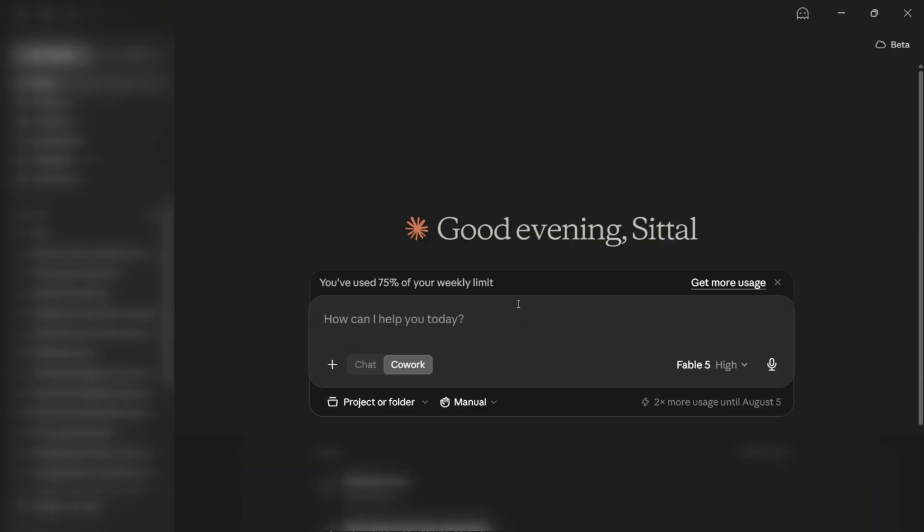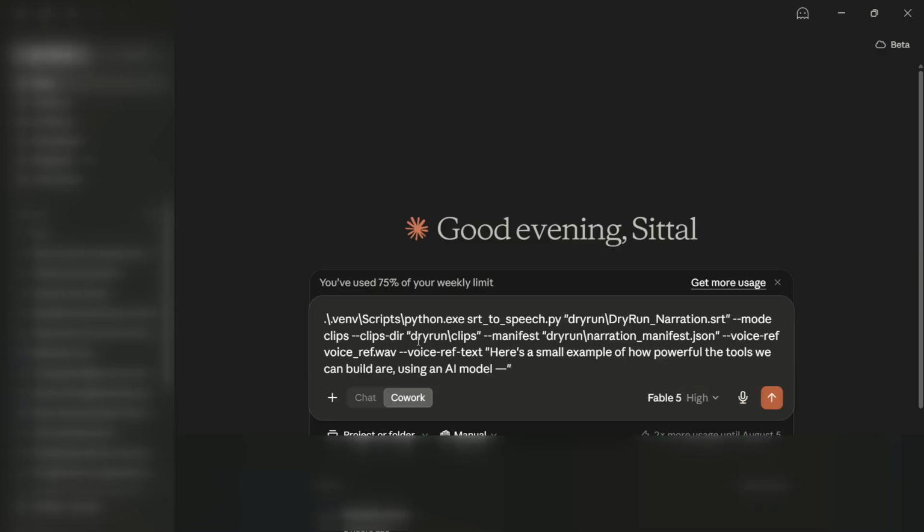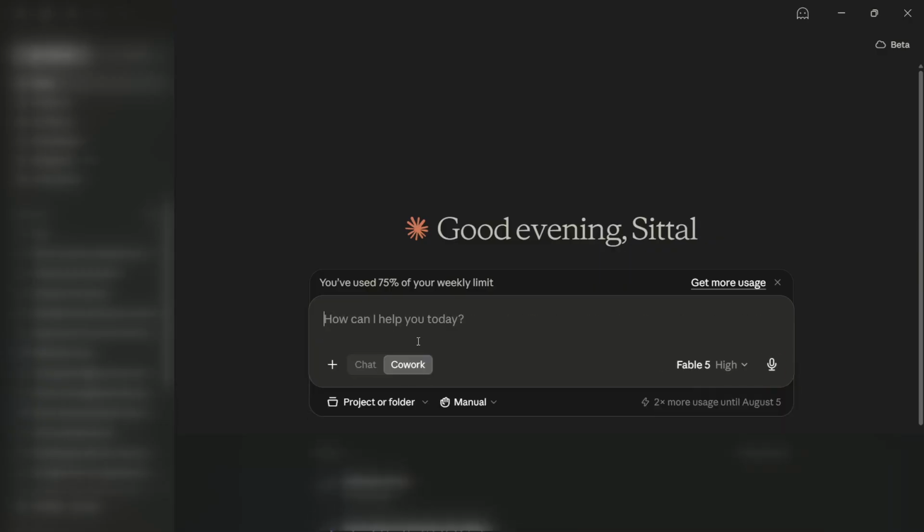You can even ask it to design an icon for the button, and it will create the icon and place it there too. Back in pyRevit, you reload, and there's your button. It may not work perfectly on the very first try. There may be a few errors. When that happens, you copy the error, paste it back to Claude, and it reworks the code and replaces the previous version. Then you reload again, and you keep going until the button does exactly the job you want.